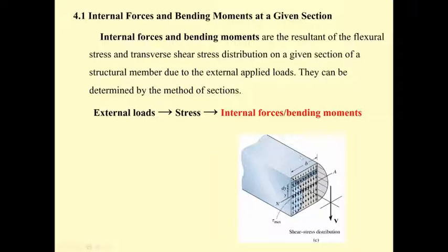It is the normal stress due to the normal force, the shear stress due to the shear force, and the bending stress or flexural stress due to the bending moment. So, if you know the stress, actually the stress will produce the internal forces and the bending moment.